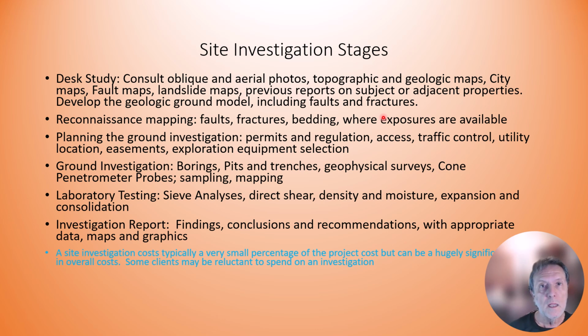We go out with a site plan and with all this pre-acquired knowledge of the site and do our borings, our pits, our trenches, geophysical surveys if those are warranted, on sites where we possibly may have deep, loose alluvium, groundwater. We might do cone penetrometers where, let's say for example, in the LA Valley areas, alluvium is very deep, very thick, so we may want to go 100 plus feet with our probes, which lends itself to an investigation using cone penetrometers. I'll get you more detail on that kind of exploration equipment later. Okay, so we're going to drill, dig, we're going to get samples, we're going to do mapping.